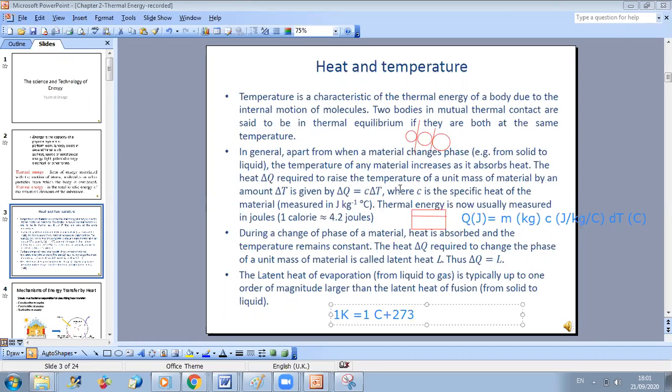Now, if you want to define the heat required per unit mass, okay. So if you want to define it per unit mass, this means that you will give it in joule per kilogram, and then you don't need to have M. Okay. So if you define heat per unit mass, then it will be, let's say, small q in joule per kilogram. It will be defined only as C times delta T. Okay. So it's like you are dividing big Q by the mass M.